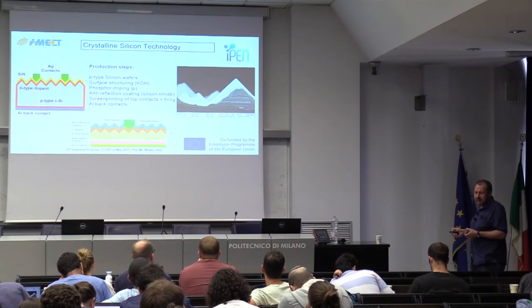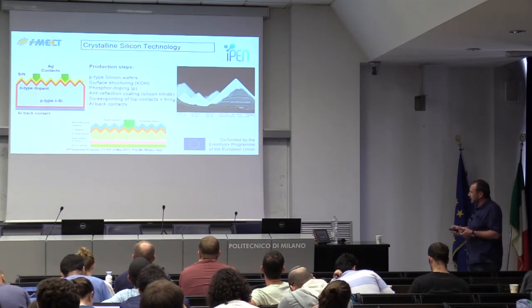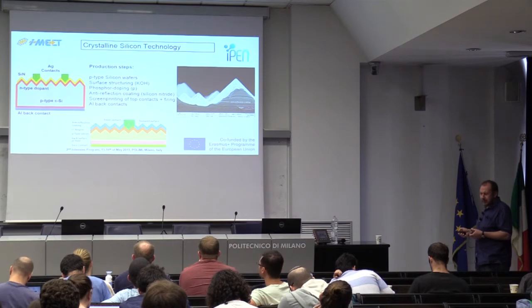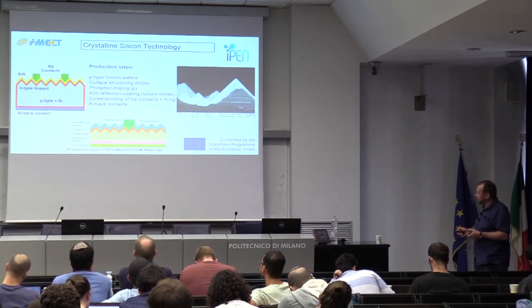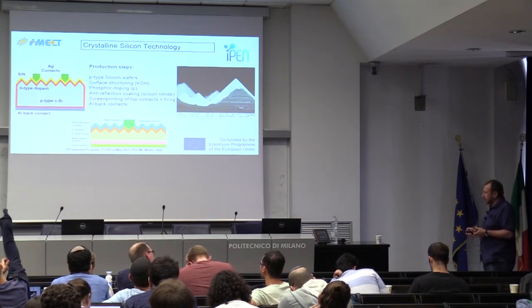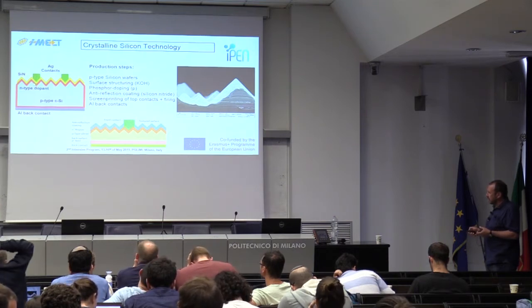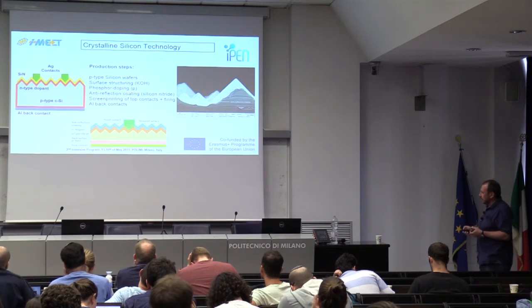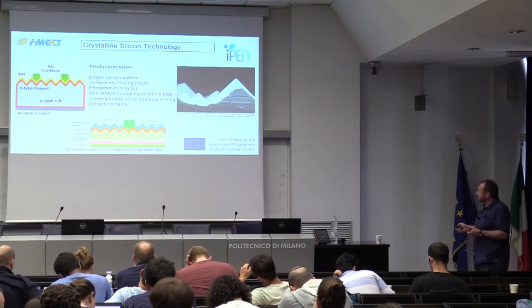There is a metallic paste containing silver and lead oxide. It is screen printed on the top. Then the solar cell is heated up, and this remelts the anti-reflection coating, and in this way there will be a contact, which is not shown actually in this figure, to the silicon bulk.